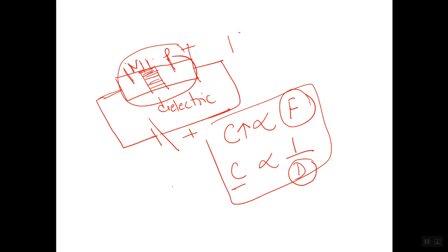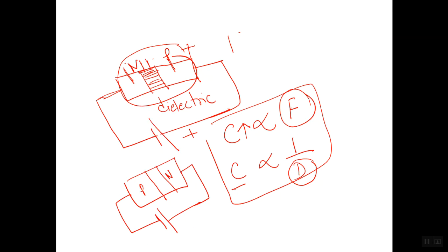And what is transition capacitance? Same way, when this diode is connected to a battery in reverse bias condition. Now see, you think this is P, this is N. Now see what will happen, this gap will increase, means the width of the depletion layer will increase in reverse bias condition, and it means when distance is increasing, capacitance will be less.